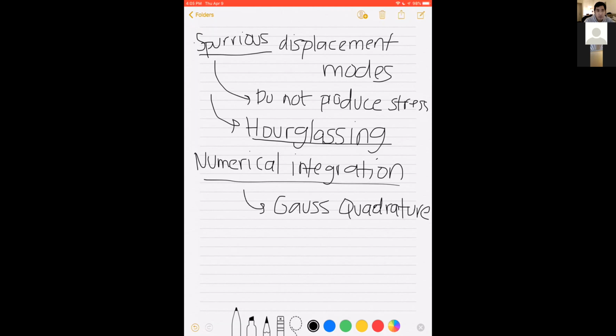So there's the same effect that we get for mesh refinement, where if you want more accuracy from your Gauss Quadrature, you need to do a little bit more work and a little bit more computations. So what can happen sometimes if you're using a very low order Gauss Quadrature, so some terms you might see in some software. I haven't seen this in Ansys yet, but in other software you can definitely control this. It's often called reduced integration.